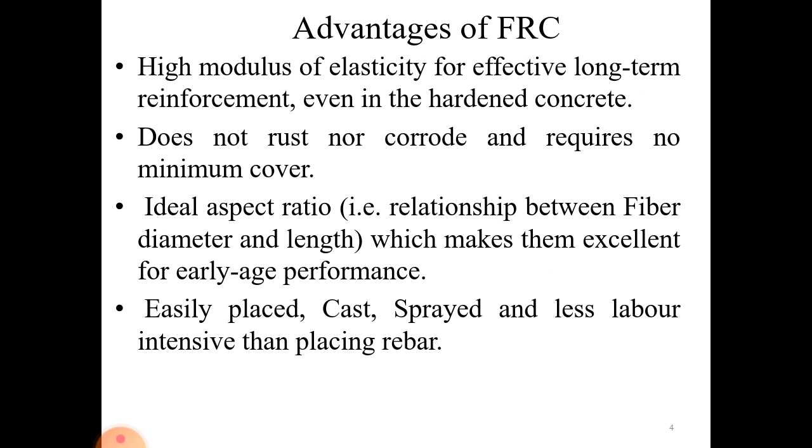Now, what are the advantages of FRC? High modulus of elasticity for effective long-term reinforcement. Then it won't rust or corrode easily and requires no minimum cover. Then ideal aspect ratio, which makes them an excellent thing for early age performance. Then what is ideal aspect ratio? It is nothing but a relation between fiber diameter and length.